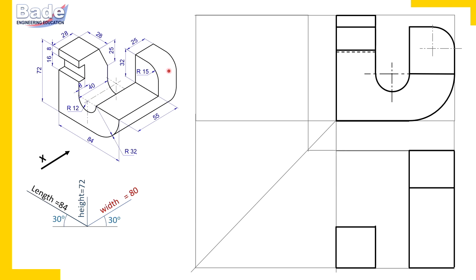The boundary of a curved surface, also called boundary generators, we make dark. Those are not edges, but boundary generators. Remember, there is a curved surface here, and this line is the boundary of that curved surface. So it can be considered the boundary generator of this quarter circular, quarter cylindrical surface. Okay, so we have completed this surface in the top view.